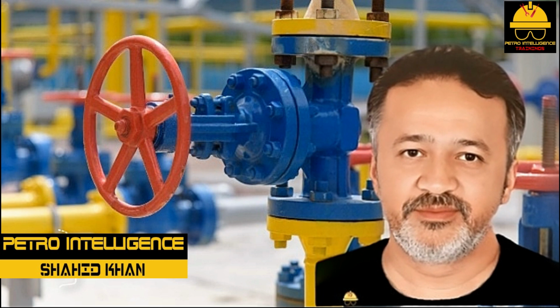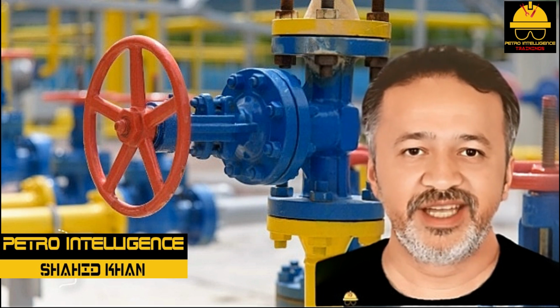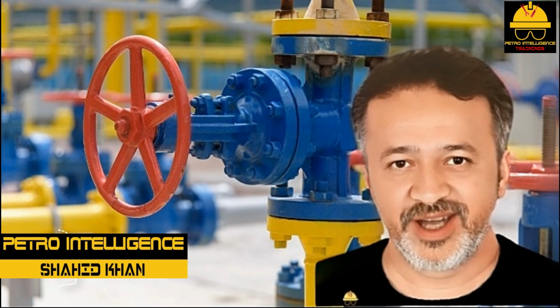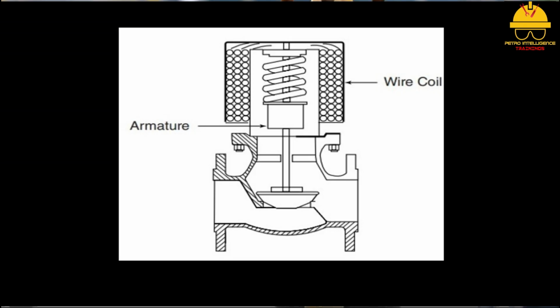Electric actuators. Electrically operated actuators convert electricity to mechanical energy. Examples are the solenoid valve and the motor-driven actuator. Solenoid valves are designed for on-off service. The internal structure of a solenoid resembles that of a globe valve, as shown in the picture.